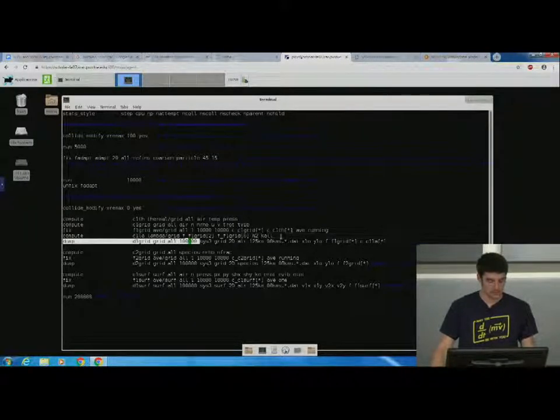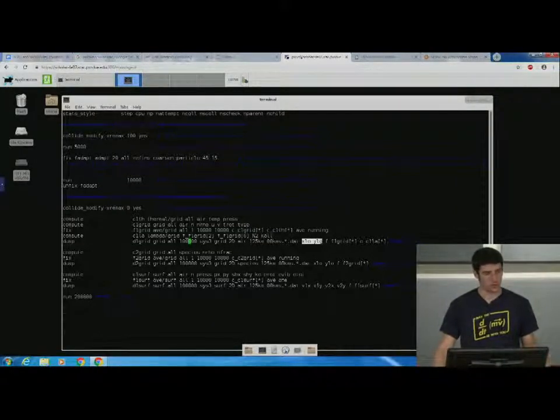Then I'm saying the file name I'm outputting here. This asterisk means that it's going to be the step number. And then I'm outputting my coordinates, so my x and y coordinates of each cell. And then here I'm saying I'm outputting a fix command with this ID, which is this fix command here.